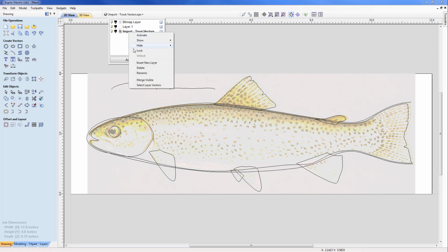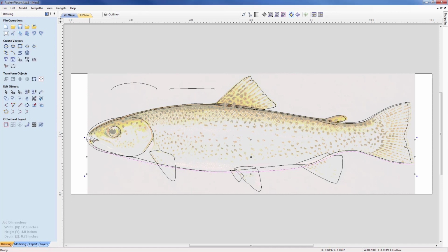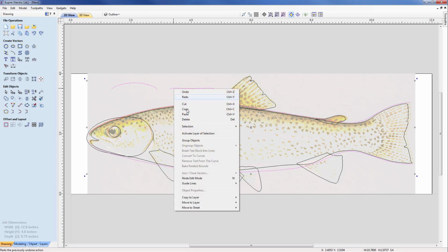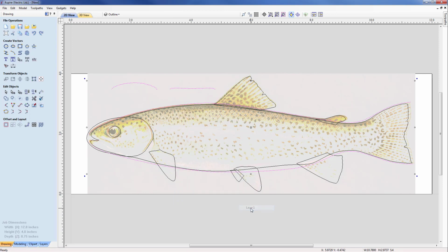So what I'm going to do firstly is just rename this, and we're going to call this just outline, okay? And then we're going to take a selection of these vectors and put them onto layer 1 and rename that. So I'm just going to take the vectors that will form the 2 rail sweep surface. I'm going to shift and pick the other vector here and then the 2 cross sections, and we're going to move to layer 1, okay? And then I'm just going to rename this. So this is going to be called basic shape. This is going to be the underlying basic shape. So with that, we will now move those vectors onto that layer.